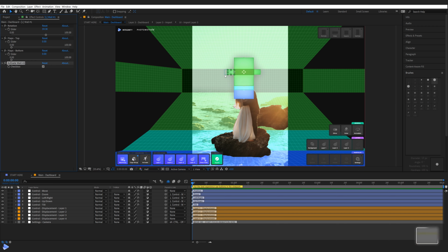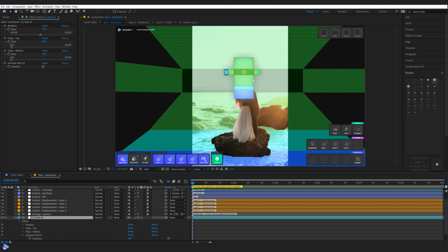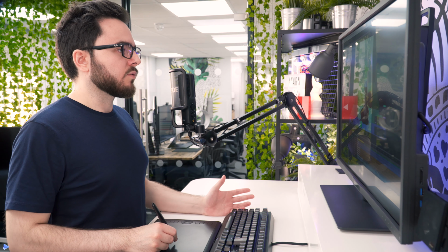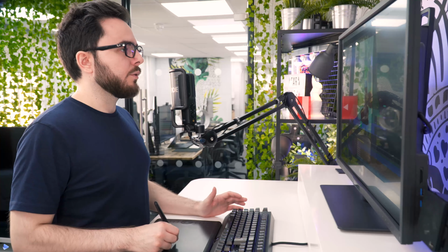And just to mention this, obviously these extensions work across this whole controller, so you can keep extending walls if you have different angles of your walls. So if you are doing buildings or stuff like that, these walls will make that possible. Same with the roof as well. If you have something uneven on your roof, you can keep extending those things and achieve whatever you really want to do. I mean, as I mentioned, those flaps, for example, if you select that wall so we can focus on that area here, you have flaps top and flaps bottom.